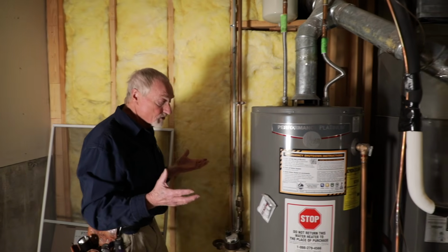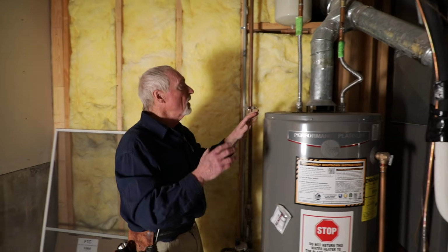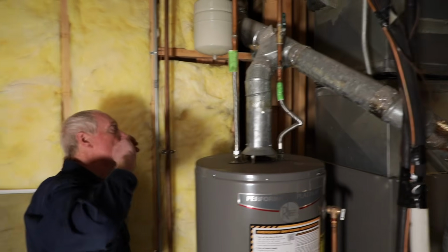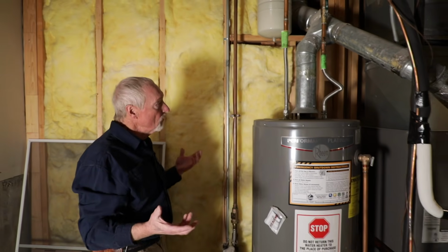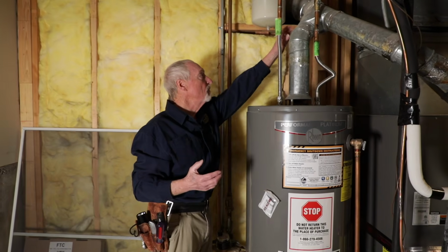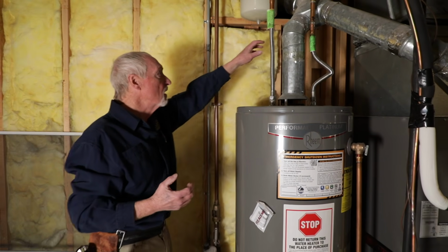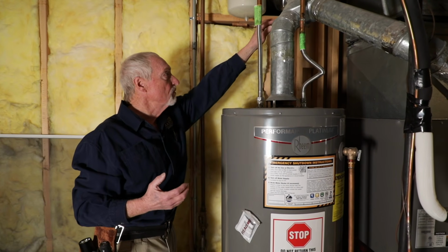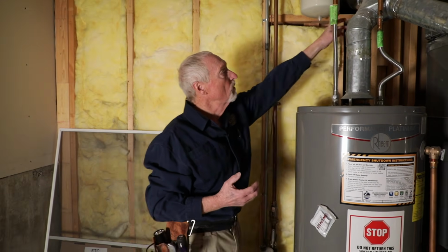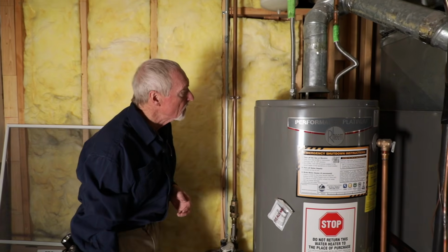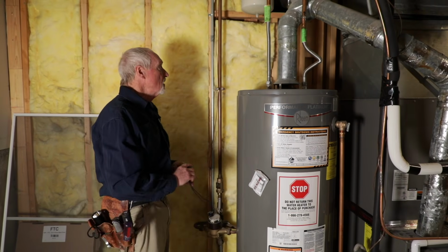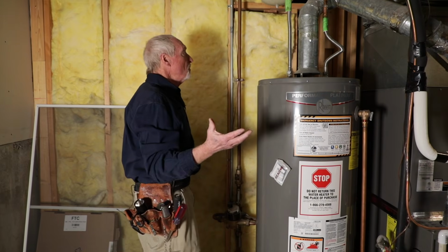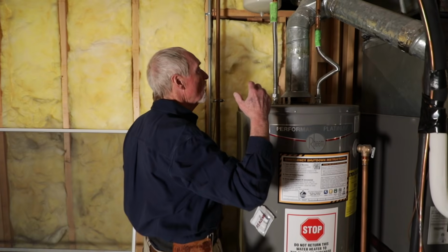So while we're all standing here with our water heater, we see right out of the gate we have foil tape up here on the flue, and once again, foil tape not allowed in most areas. It hides the quality of the connection, and it's not approved for use most of the time. And so we would call that out as a defect. So I would take my camera and take a photo of that. Even if it's a minor defect, it's still something we want to point out.